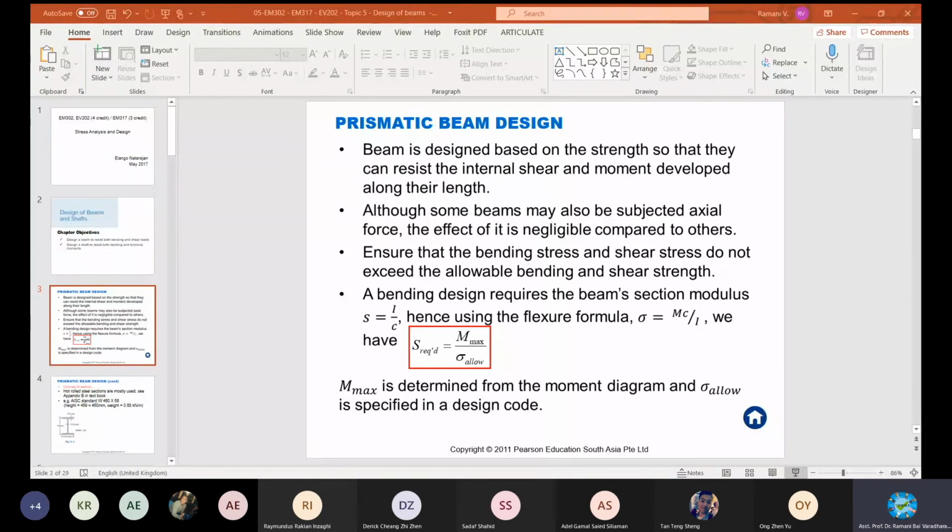Wherever there is hogging and sagging, if there is a bending like this, by providing the reinforcement at the bottom, it can be straightened, right? It can still bear the loading, right? Due to loading, if it is bending like this, you see this is the extension, the elongation. By providing the steel rod at the bottom, you can keep the member in a good position like this. Okay, I will show you the proper diagrams and videos so you can understand better.